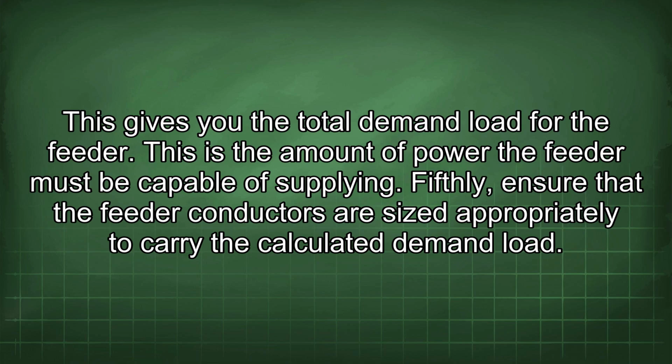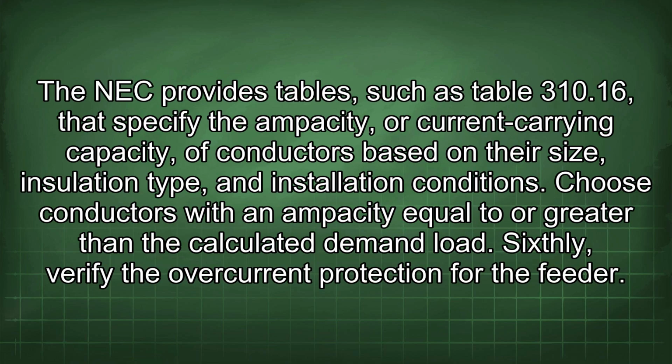Fifthly, ensure that the feeder conductors are sized appropriately to carry the calculated demand load. The NEC provides tables, such as Table 310.16, that specify the ampacity, or current carrying capacity, of conductors based on their size, insulation type, and installation conditions. Choose conductors with an ampacity equal to or greater than the calculated demand load.